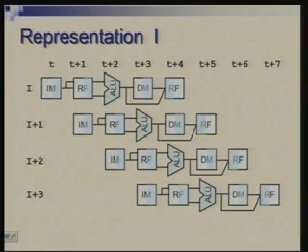On the other hand, the way we have chosen our memory is that it can either do read or write at the same time. So therefore, trying to share DM and IM would not have worked out. For example, you would notice that in cycle t plus 3, I is using DM and I plus 3 is using IM, and if this memory is not capable of doing one read here and one read there, then there would have been a problem.